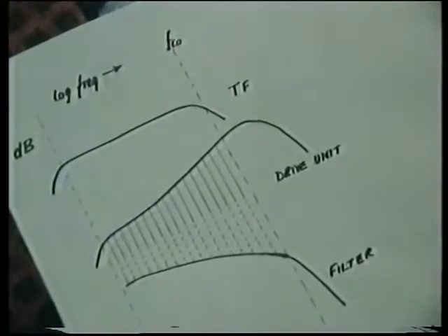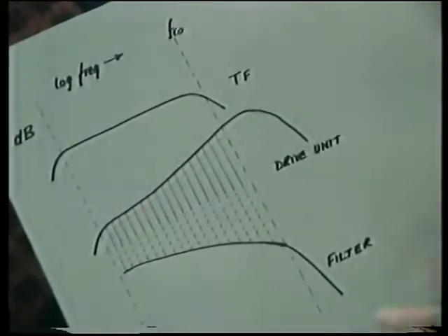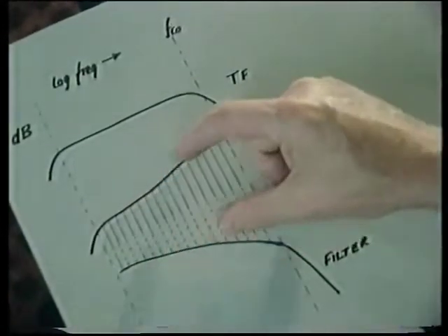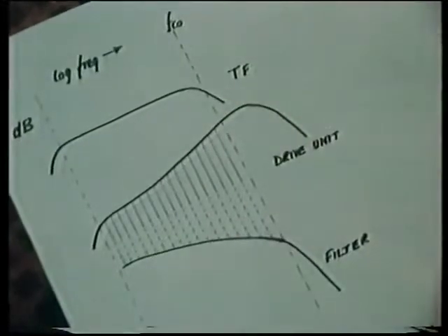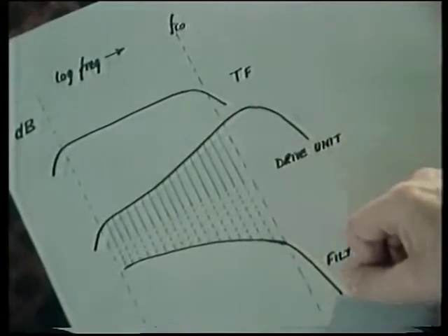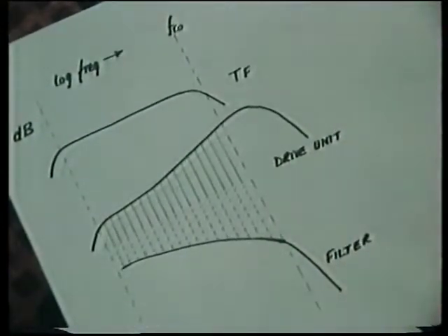We then derive, by calculation, an inverse frequency characteristic, such as we see here, which not only corrects the response in the pass band, but also adjusts the response at the cutoff frequency and beyond it, because we find it necessary to control the response of the combination of the filter and its drive unit to something like 40 dB below the general level in order to have a very good marriage and inaudible joints in the various sections.